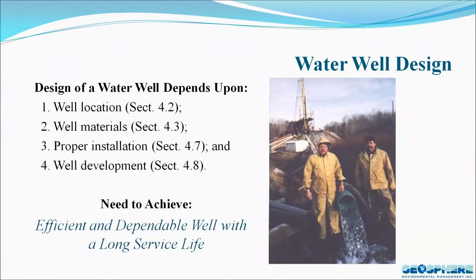We want to make sure that we remove as many of the fine materials around the well screen from the formation as we can in order to make the well as efficient as we possibly can given the design. Now, what we're trying to achieve here is an efficient and dependable well with a long service life, like 75 years or so. This is what we're trying to get out of this, because wells are expensive to put in, land is expensive to purchase, so we want to make sure that we do it right at the beginning because it's going to be there for a long time.